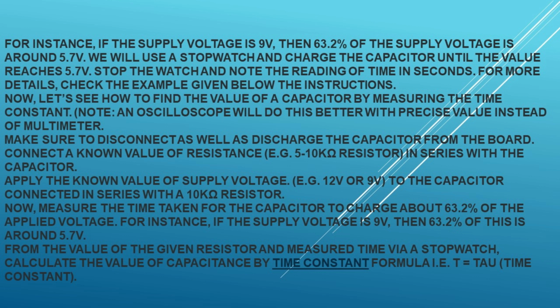Also, you can use the DC voltage V mode in the digital or analog multimeter to perform this test. Make sure to disconnect a single lead, no worries if positive, long, or negative, short, of the capacitor from the circuit, or you may fully disconnect it as well if needed.